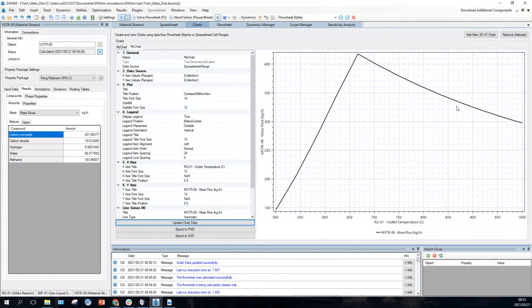Can we do that by adding the absorber as a second independent variable or not in the sensitivity analysis? Yes, you could. The trouble with the sensitivity analysis is that it crashes if you've got the wrong values. Like with me, it crashed even on the base case for some strange reason. So I just took it out so that the simulation would be more stable. I took out the absorber.